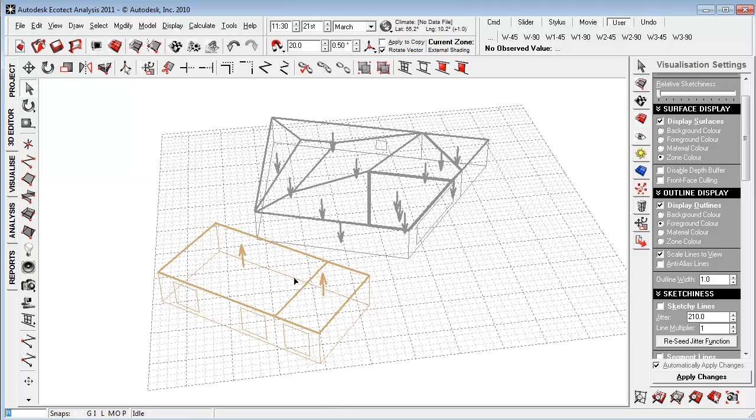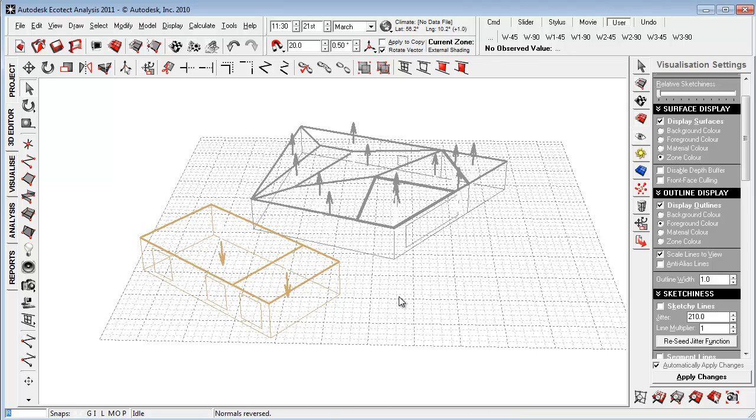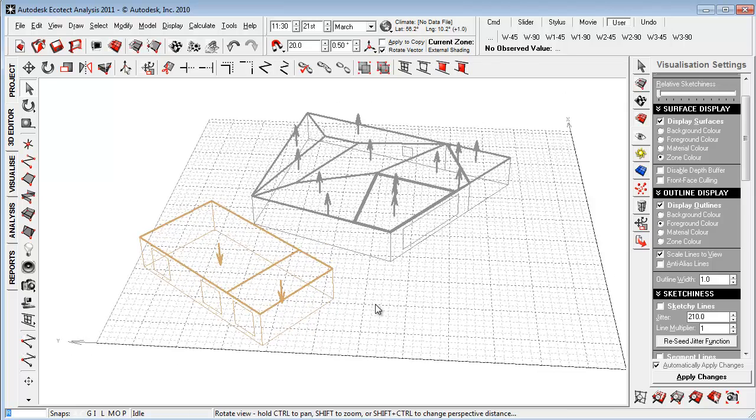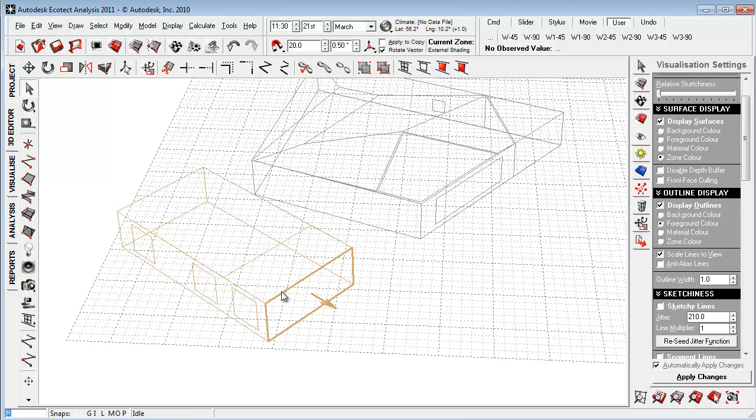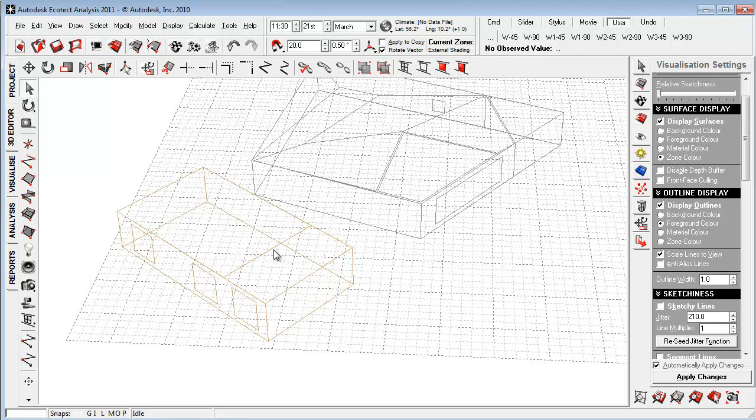And if I hadn't flipped these before, I could now just say Control R and flip all the surfaces again. Okay, I might not need to have these two divided in two, so I want to delete this surface here, double click to go into node mode, drag and select these two nodes and then say Control R, and now I've updated that zone.